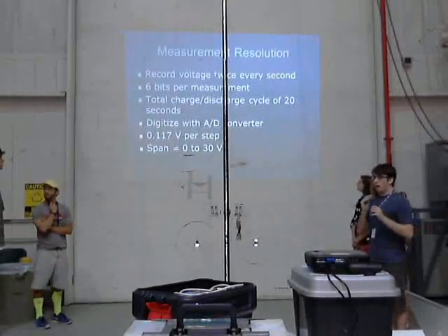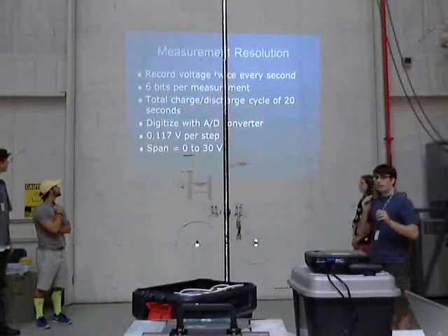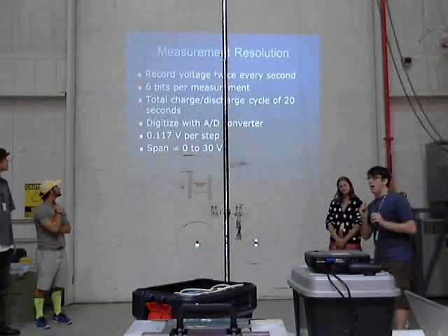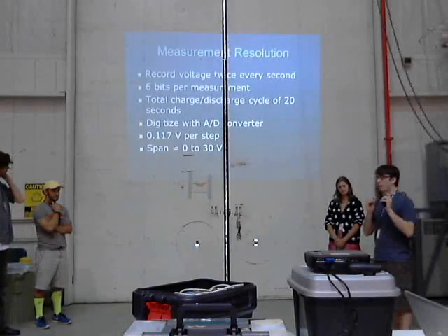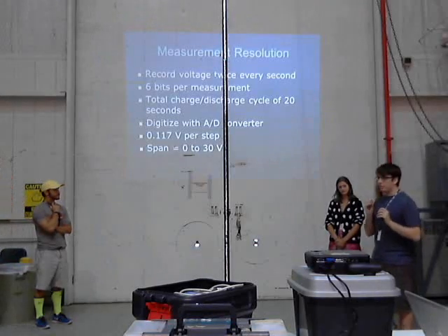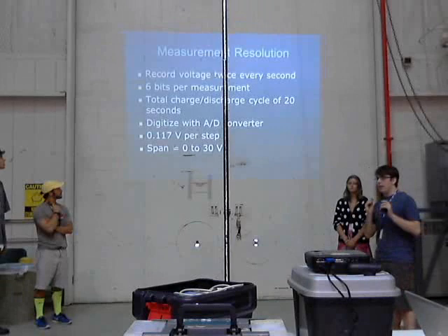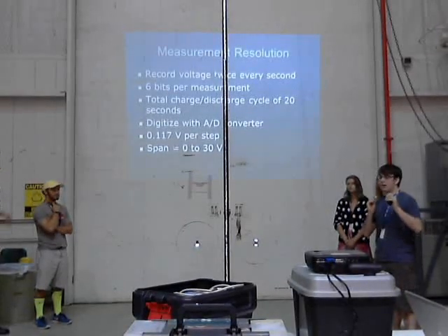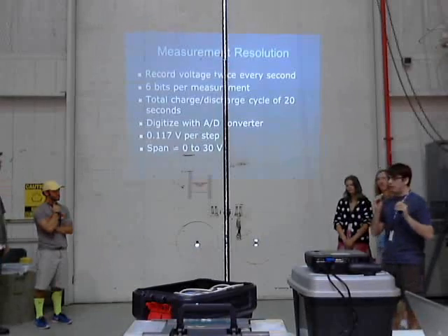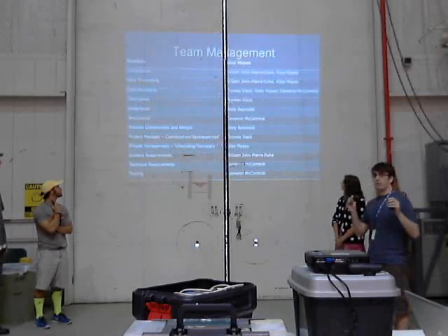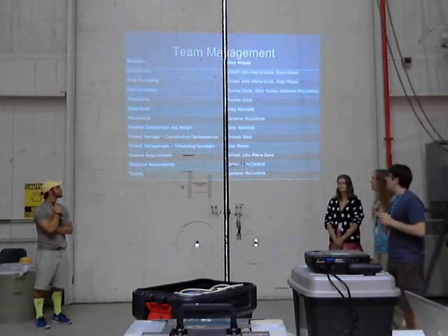Okay, and so the data acquisition part, which I hadn't talked about before: basically we're taking one measurement every 2 minutes, and each measurement is about 240 bits. We're estimating the total flight time to be about 85 minutes, and that gives us about a 10,200 bit limit. And our span is from 0 to 30 volts.